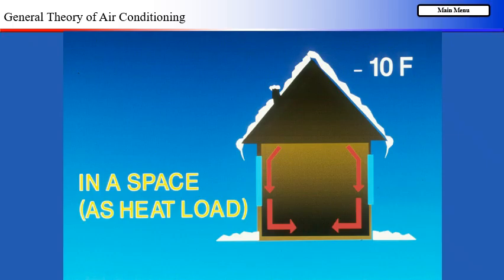In cold climates, convection causes heavy cold air to form a downdraft off outside walls and especially windows. As new air rushes in behind that which falls off the windows, heat is transferred from above the windows down to the window where it becomes a heat loss for the space. In this case, convection causes discomfort because of the cold puddle of air which builds up on the floor.